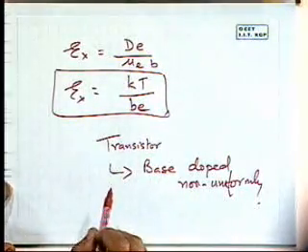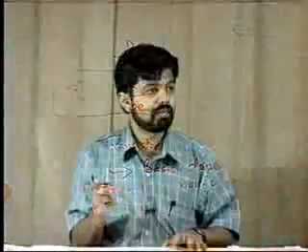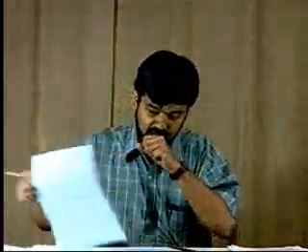And we will see that what it does is to speed up the flow of carriers through it, because in addition to the applied fields, there is this built-in potential too that aids that process. So it makes the transistor faster because of this action of a built-in potential being developed in it. So it's not simply an academic, it's got a nice application also there.